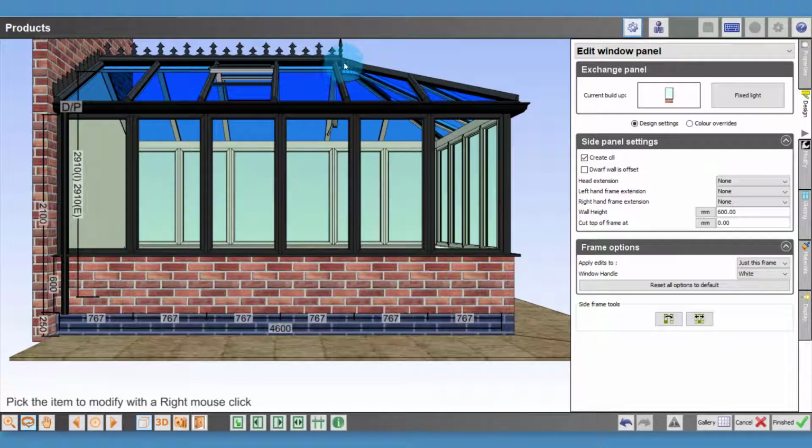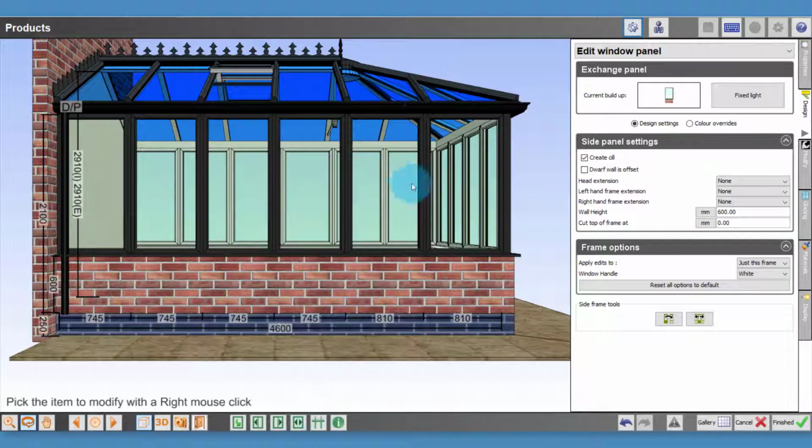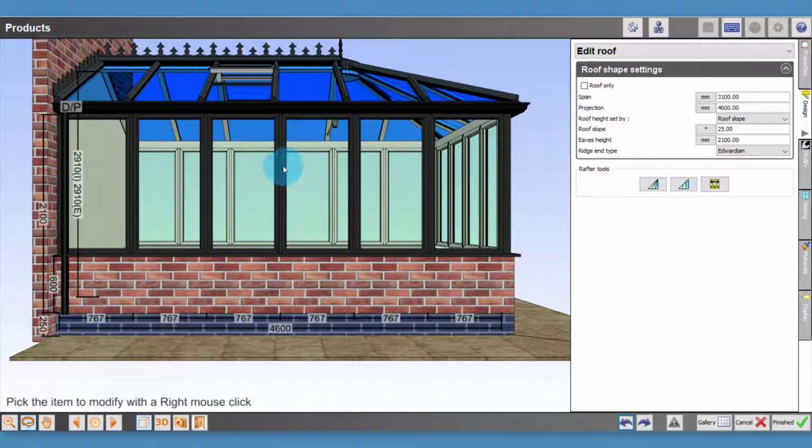Remember, we changed the rafter spacing to provide a certain amount of clearance here at the end of the ridge. This is why you've now got this misalignment. It'd probably be wise to correct that misalignment by using this very useful function here to align your windows with the rafter spacings. There is always more than one way to do this.